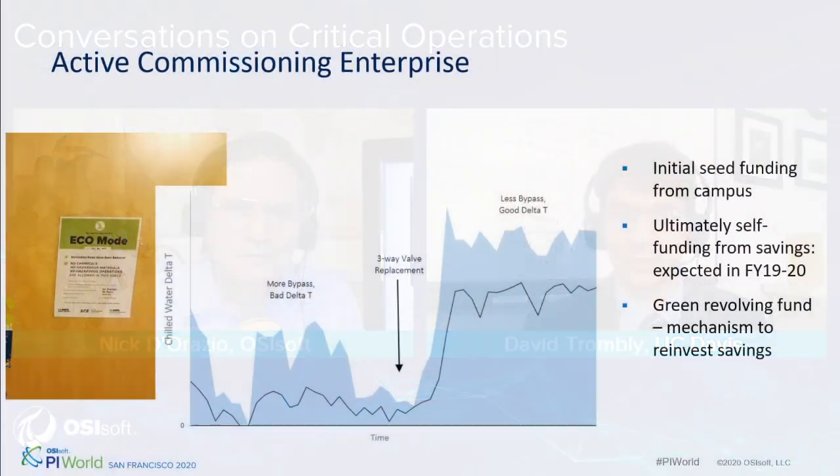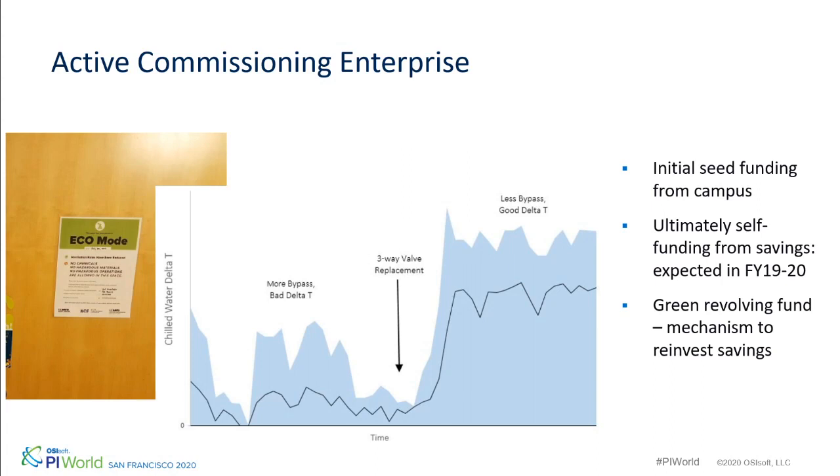And so if buildings are not using the cooling they're getting and are returning water at a much higher temperature back to the chiller, then that impacts chiller efficiency. So essentially, exposing the data from both systems made us able to see which buildings were impacting chiller efficiency, and then ultimately see the results on chiller efficiency. We've got some slides. We're looking at the delta T screen.